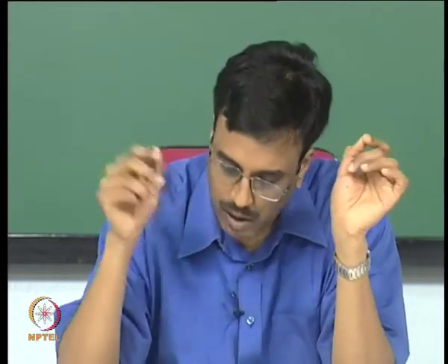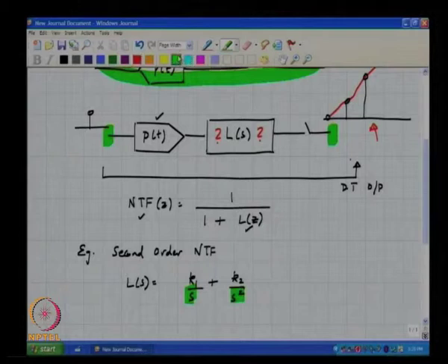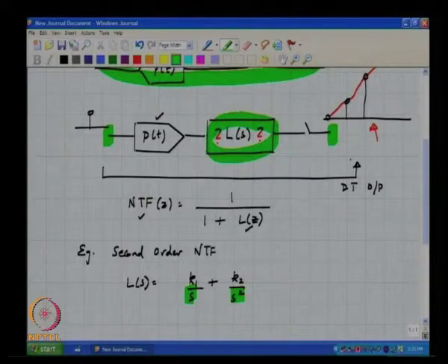Which means that if I am able to synthesize a continuous time filter whose impulse response is this L of t that we found here and multiplied it up by cos 2 pi into n times t, where n can be any arbitrary integer, then even though the absolute impulse response will look totally different, the samples of the response will look exactly the same. So this is telling you that it is possible to have any number of continuous time filters whose sampled response is what you want, okay, all right.